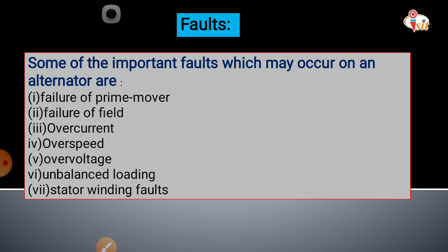And second, the overload protection for the alternator is such that the protection might disconnect the alternator from the power plant bus on account of some troubles outside the plant. So these are some reasons against overcurrent protection, but the main reason for the overcurrent is the partial breakdown of insulation and the overload.